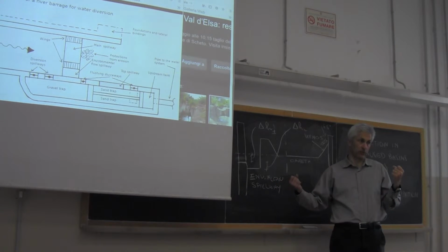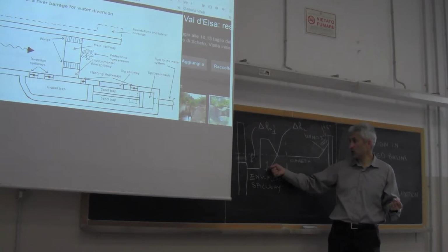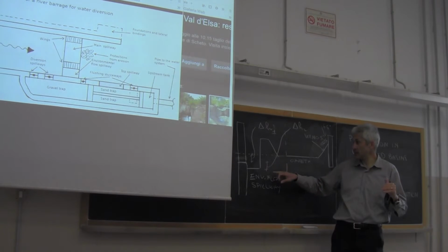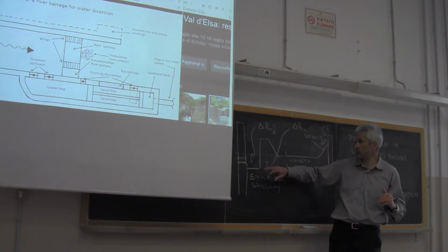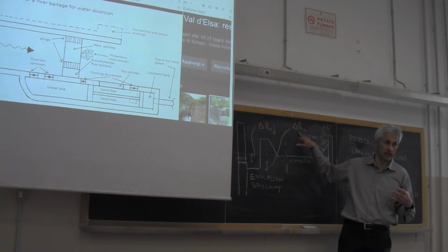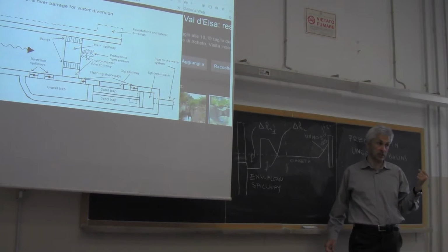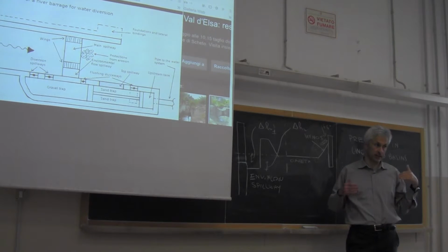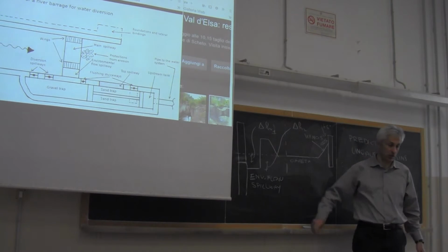that flows through the environmental flow spillway in the presence of a water head that is equivalent to the level of the environmental flow spillway plus delta H2. Okay? And we have a relationship that is suggested by hydraulics for computing the flow through a spillway. The same relationship will be used to determine delta H1.